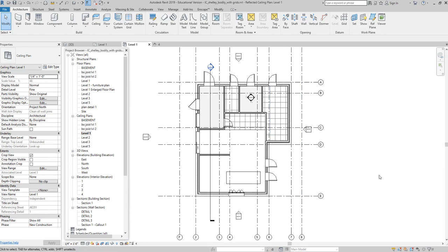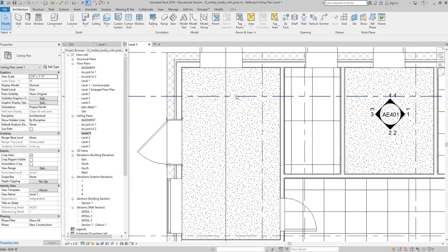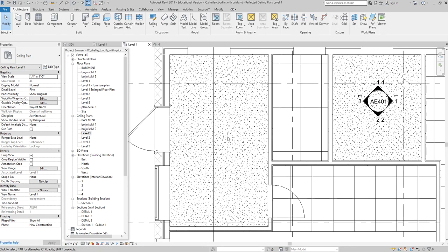All right, so let's see. We can alter the assembly. We can draw them using auto and sketch. We can look at building sections to align them to the structure above. We know that we should create a ceiling. We don't want to just add a finish to the bottom of our floors because these are defined as hosting elements for things, for ceilings, okay? So before, when I tried to place a light on the underside of my floor, which I had a piece of gypsum board defined to, it didn't work.